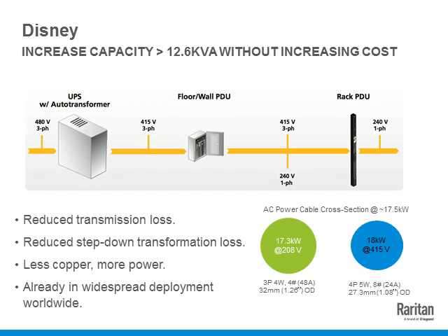It shows up in the amount of money you spend on laying the circuits. The circuits are cheaper. The power strips are cheaper because the inlet cords use less copper. And by the way, this is something that's been widely used in the world, in Europe and Asia, where 400 volts three-phase providing 230 volts line to neutral has been the standard for a long time.